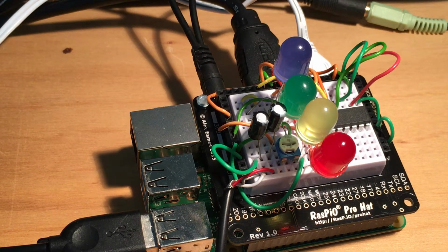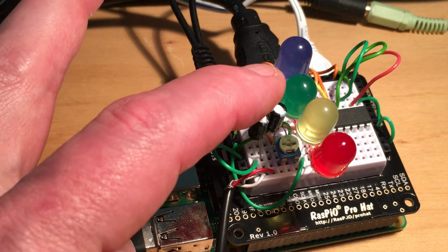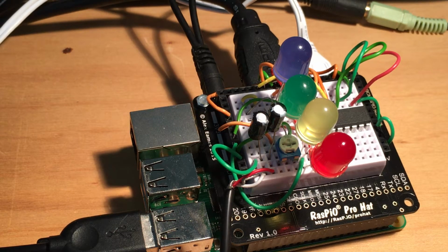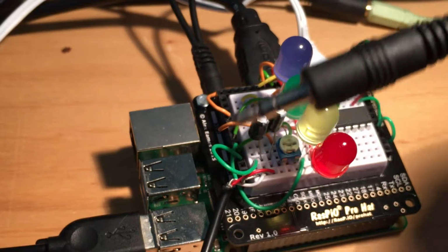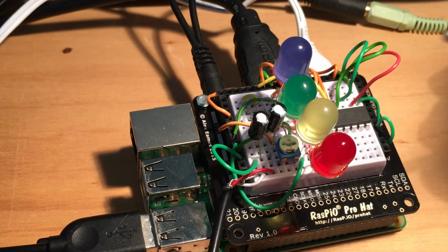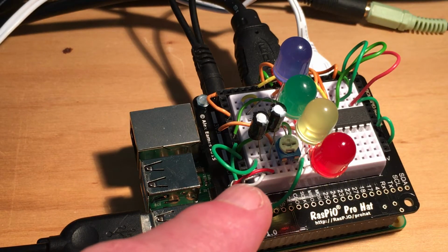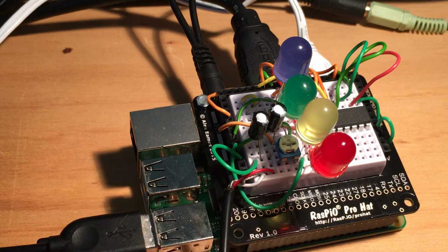The experimenter kit came with 5 LEDs, and I managed to fit 4 of them onto the board, each of them driven by a separate GPIO input, and also to use a couple of extra components, 2 10 microfarad capacitors which you can see here, and in addition a lead which I cut from an old audio connector lead off an old computer, which has a 3.5mm plug on one end, and I chopped it in the middle, and the 2 connections are connected into the board here.